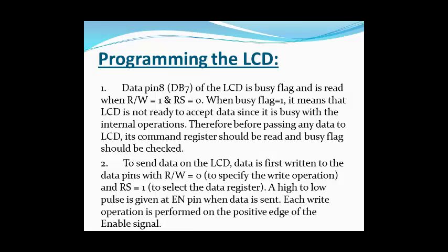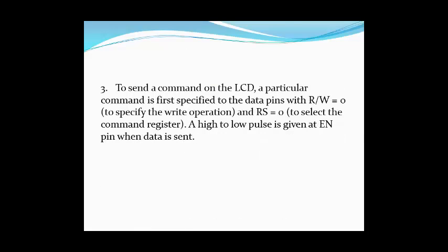To send data on the LCD, data is first written to the data pins with read write equal to 0 and register select equal to 1, and then a high to low pulse is given at the enable pin when data is sent. To send a command on the LCD, a particular command is first specified to the data pins with read write equal to 0 and register select equal to 0, and then a high to low pulse is given at the enable pin when the data is sent.